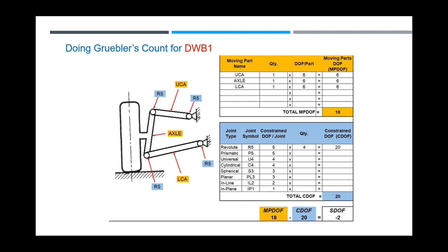So let's try to fix this mechanism. We wanted the answer to be 1 because we wanted it to rotate up and down freely, regardless of the angles that these revolute joints are at. Okay, so let's play with the numbers. Let's go to the next version here.